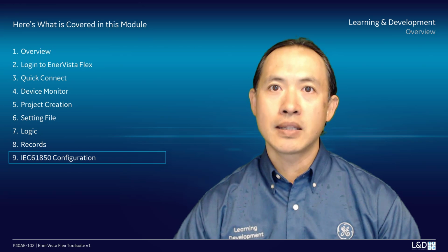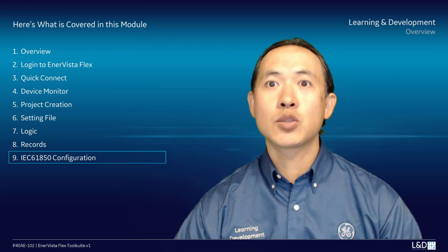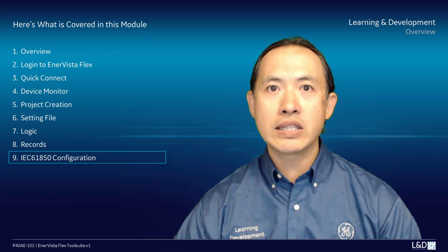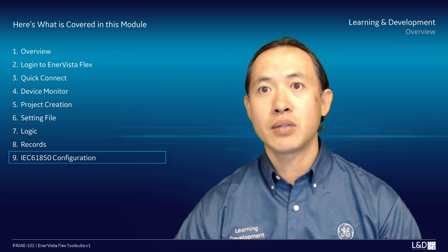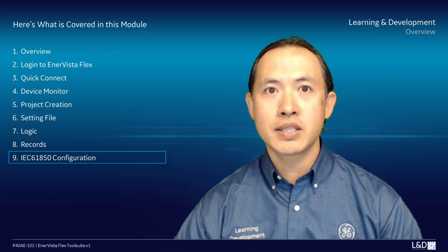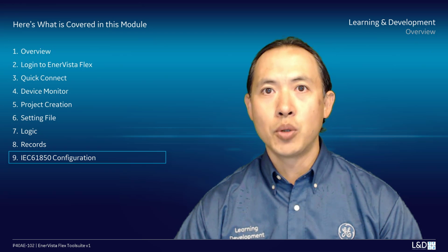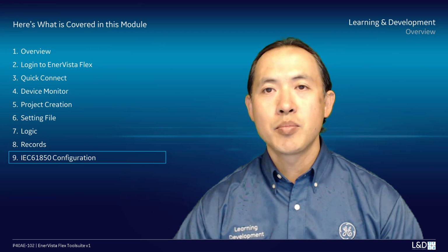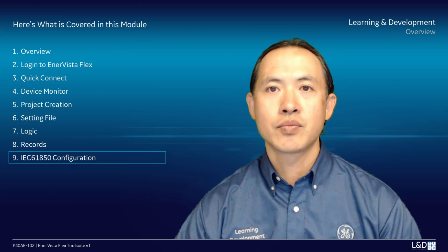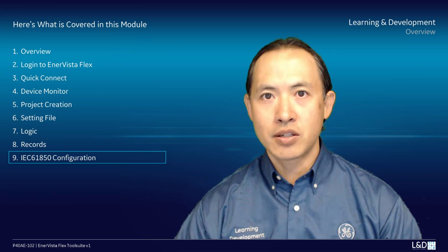And last but not least, IEC 61850 configuration. We're going to briefly show you the interface of the IEC 61850 configuration tool, how to map the external CID to the remote inputs of the P40 Agile Enhanced GGIO5. So now let's get started.